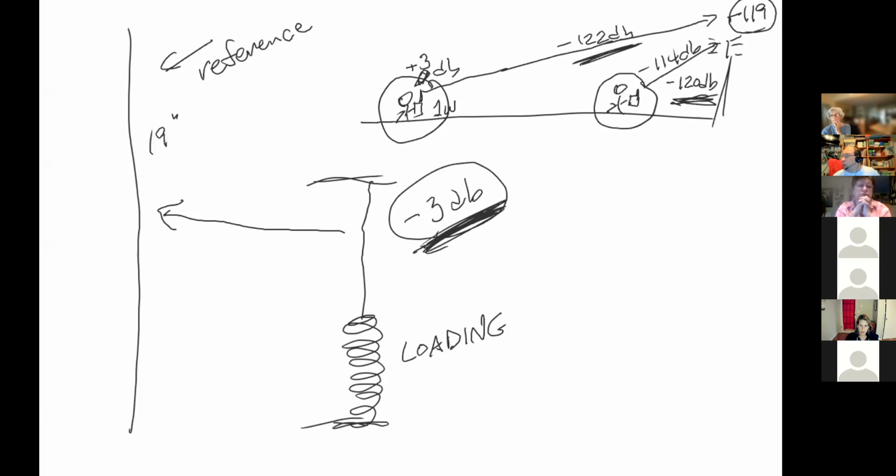Well, it's really about the loss. It's about antenna gain and loss and efficiency because of how it's put together. By virtue of taking that and coiling it up, you have killed its efficiency. But maybe that's okay. You know, it's entirely possible.